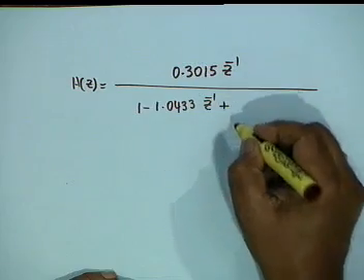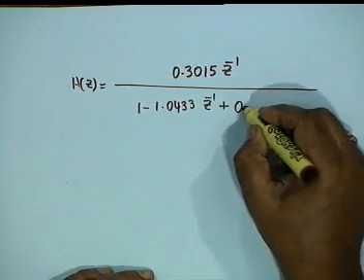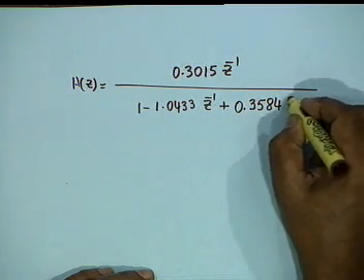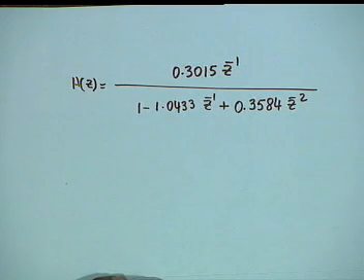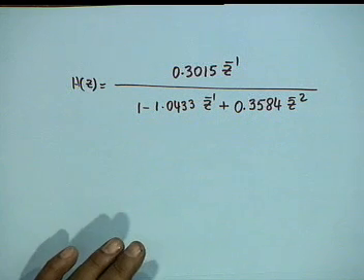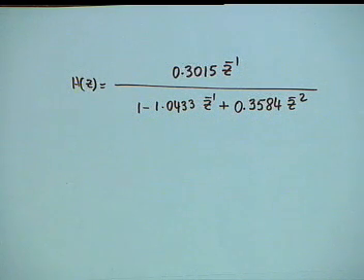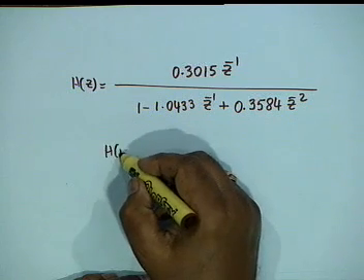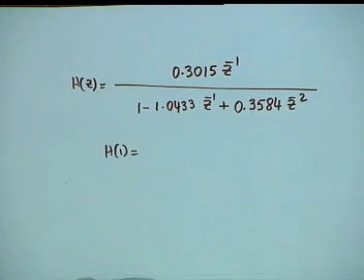I must warn you that you must keep as many digits as permitted by your calculator if you are working in an industrial environment. If you are going to make a chip out of it, you better keep as many digits as possible, because the filter design is extremely sensitive to quantization, to truncation errors.